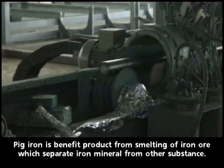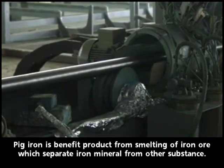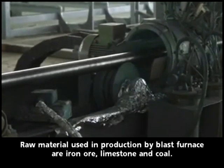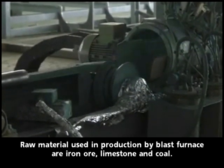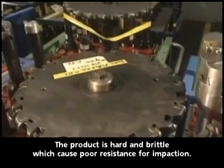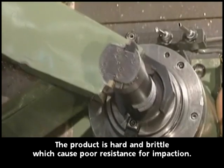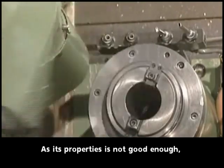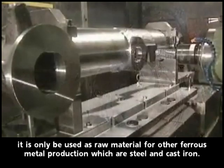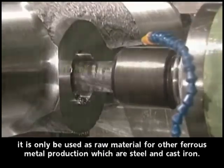Pig iron is a product from the smelting of iron ore, which separates iron mineral from other substances. Raw materials used in production by blast furnace are iron ore, limestone and coal. The product is hard and brittle, which causes poor resistance to impact. As its properties are not good enough, it is only used as raw material for other ferrous metal production, which are steel and cast iron.